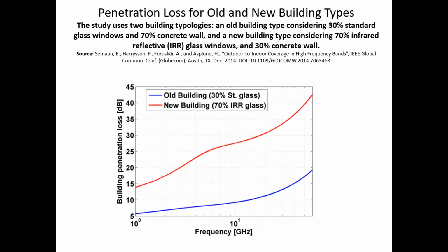It is true that the old buildings have more walls, and the windows are less for old buildings. In the new buildings, you have large windows. When you have brick walls, they can also prevent your signal a lot. So in that respect, old buildings have higher penetration loss.